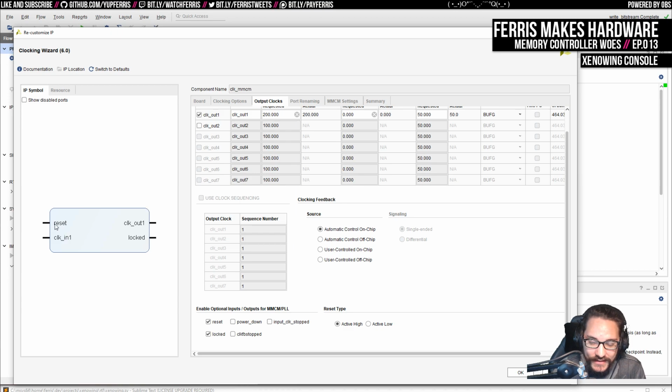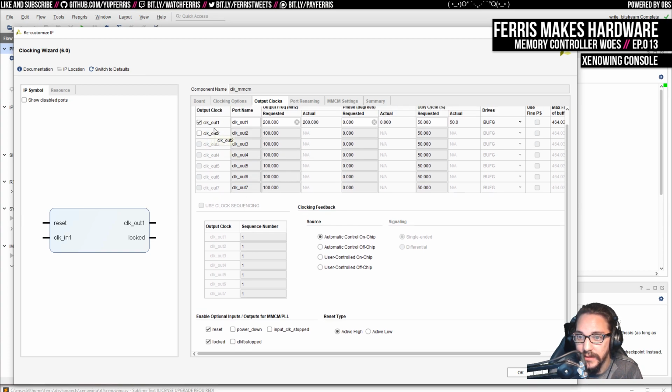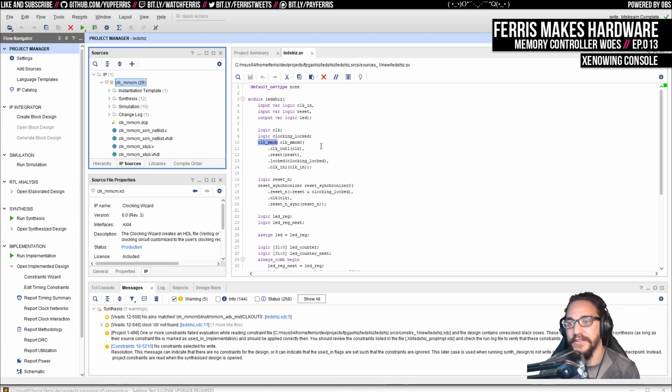But yeah, you can specify a lot of options about the clocks. And so it has this reset that's assumed to be asynchronous because you usually have a reset button on the board. In this case, whenever that's pushed, I want to reset the chip's state, and that's what this reset is going to be. And then the input clock, and again, the output clock is specified. And there's actually a couple that this can generate. Looks like it can do 2 with this same module. And I guess if you needed more, as long as the chip has more MMCMs or PLLs, you could instantiate more of these. But yeah, then you have the output clock, and then a line that says when that's locked, and I think that signal is synchronous to the clock output here. So that should be safe to use.